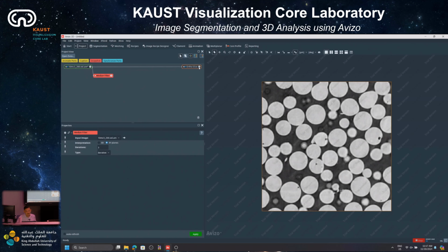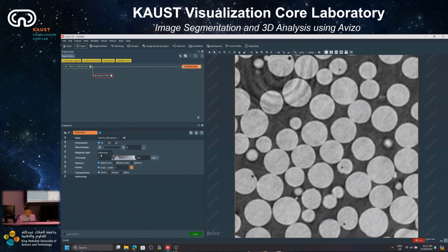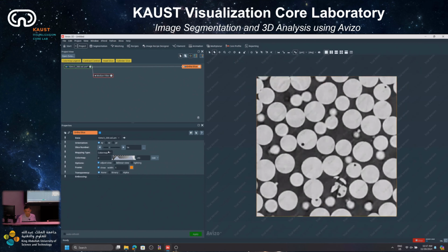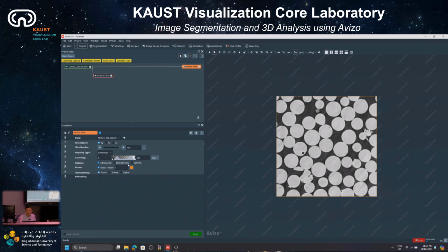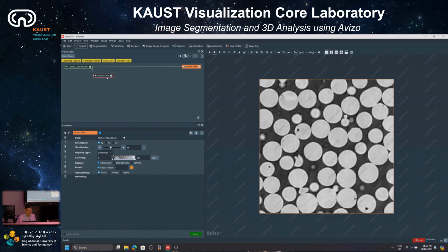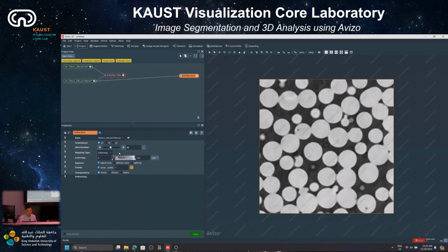Not yet. I'm not sure, because it seems to me it's not that filter. You can still see some artifact, ring artifact. And it's too big anyway to calculate the full volume. You'll see later, I'm gonna select only the region of interest to work with. Just to give you an overview, if you apply some filter, it's easier to manage the thresholding step. After the median filter, you can see the bit at the boundary of bead contact.